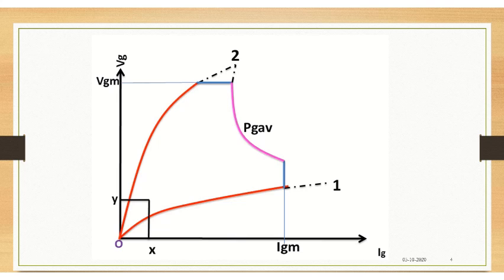Curve 1 here represents the lowest voltage values that must be applied, and curve 2 represents the highest or maximum voltage that can be safely applied to the SCR, so that you avoid any damage to the device. This minimum I will call VNG, the gate non-triggering voltage. This also will be specified by the manufacturer.